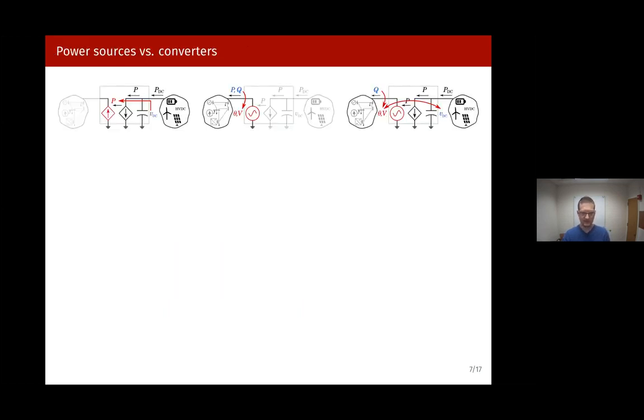Okay, so in general, what we have seen is that we may want to use a control paradigm like this when we want to do maximum power point tracking, right? So we ignore the grid, but we focus on extracting maximum power from our power source or stabilizing the DC voltage here. The AC grid forming paradigm that we've seen is basically you ignore what's behind here and you assume that somehow it can keep up with the power injection you're putting here, which is also maybe not completely viable. So what I want to propose today is a control that has a slightly different flavor, and that recognizes that the power converter as such is not a power source that you can control arbitrarily, but that it's something that can translate between the DC and the AC side, and it needs to do this as best as possible.